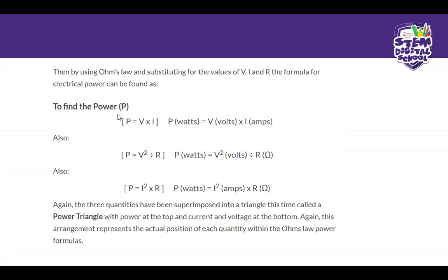The original power formula is voltage times current, but we infuse Ohm's law into this formula by breaking down the current. The current is equal to voltage divided by resistance according to Ohm's law. So when we add them together, it's going to be V times V divided by R, and that will be V squared over R. Or for example, if we decide that we want to substitute the voltage part, this usually happens, guys, according to what is given.